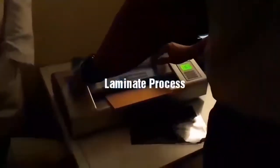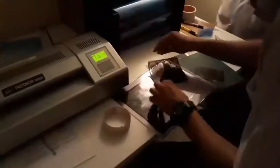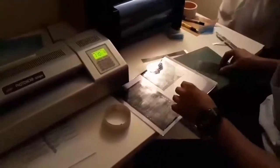The first step is the board preparation. The copper on the PCB is cleaned. Next step is the laminate process. The dry resist film is laminated on the PCB using this machine. The dry resist film is heated so it can stick on the PCB. Next, the circuit layer is stuck to the laminated PCB. Make sure there is no fault in the process because there may be errors in the PCB circuit.